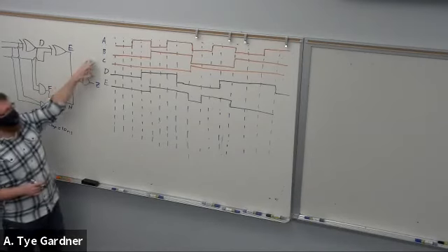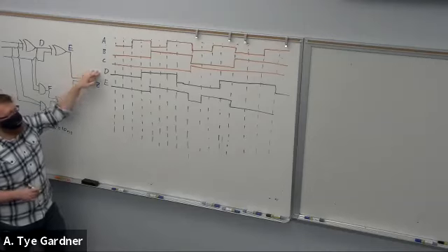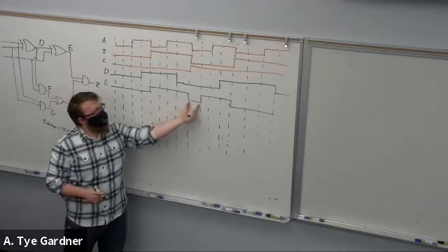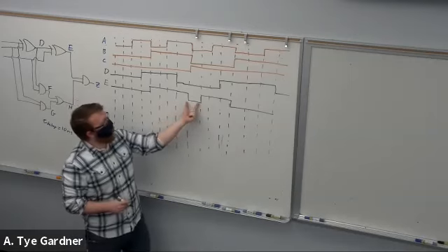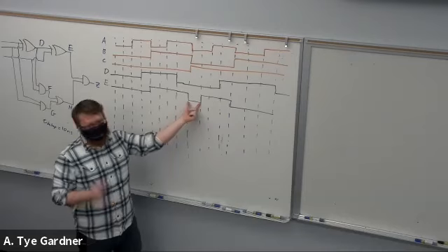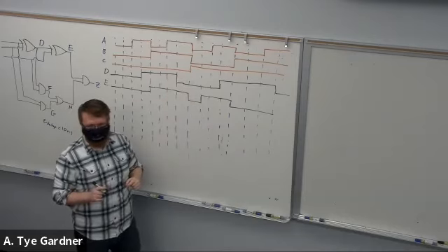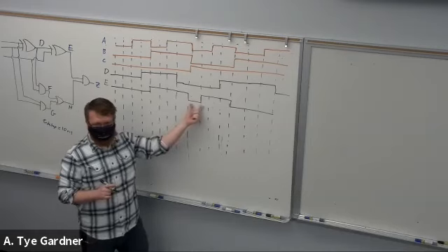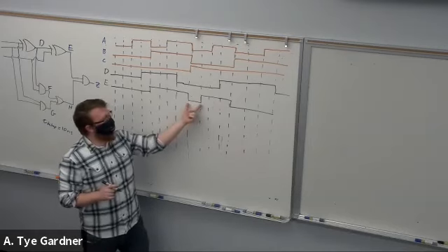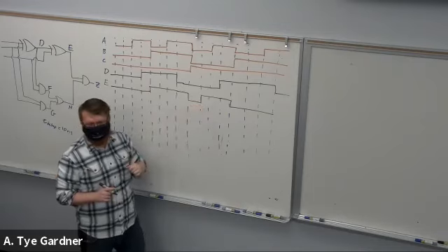Especially when you have one that has no delay path and one that does, you can end up in situations like this, and this is a perfect example of that. Notice how this is a 10 nanosecond space, even though my changes happen at 20 nanosecond intervals. So this ends up being a smaller period of time, so it's possible with certain delay chains you can miss this number entirely in this test.